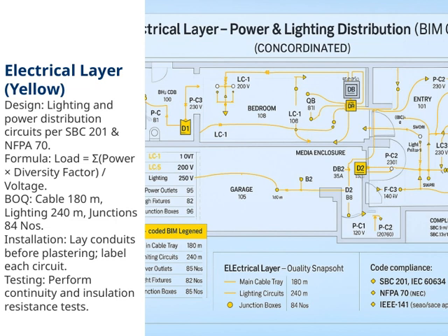Finally, testing is a vital step. We perform both continuity tests to verify the wiring connections are correct and insulation resistance tests to confirm there are no leaks or faults. These steps help ensure our electrical system is safe, reliable, and ready for use.